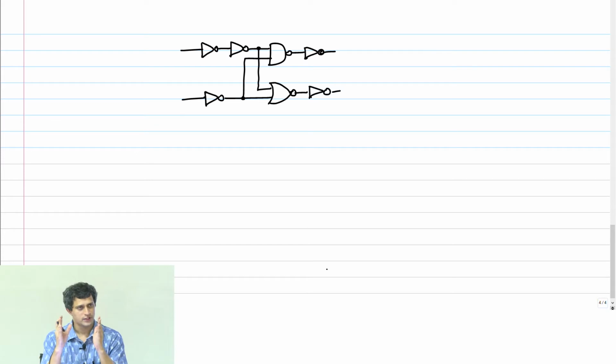So first we will do what is known as static timing analysis. Timing analysis is something that you do on a circuit given that the sizing has been done already, which means that the delay of that gate is fixed. Okay, we'll solve the sizing problem next.